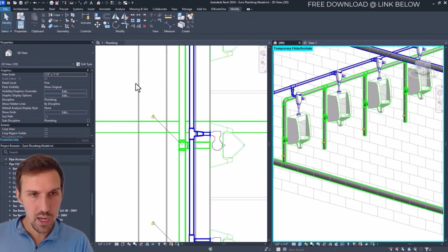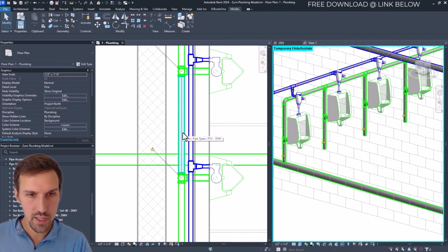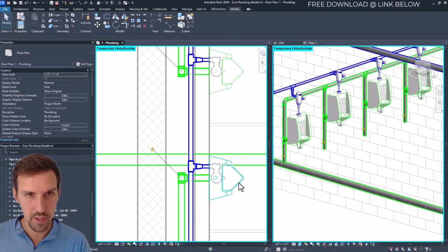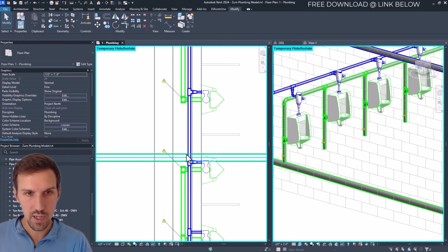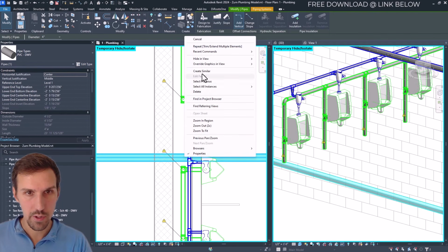What I'm going to do is I'm going to kind of create the floor plan, kind of clean it up a little bit. So the first thing I might want to do is click on this piece of pipe, and I don't necessarily want to see this when I'm modeling. So I'm going to go down to the little glasses and hide the element. And then I'm going to start drawing some piping from my main, just like last time. So we'll click on Create Pipe or Create Similar.